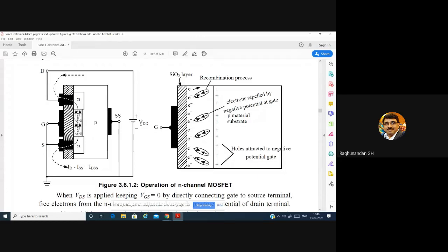So this was connected to the plus VDD, that is positive voltage, right? When positive voltage is connected to this particular metallic contact, what happens during that time? Here, a kind of positive electric field is created, or positive voltage is created at this point. Since the electrons are negative, this electric field creates a kind of attraction for the electrons at this layer.